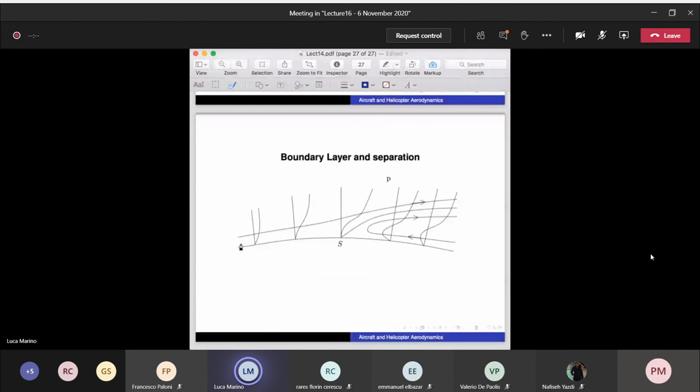So you start from positive favorable pressure gradient. So as you see, the distribution of the velocity has always the same concavity. Then from this profile to this one, the difference is that here the dp over dx is no more negative, but it is positive. So something is going to happen, and so the velocity will have different sign.